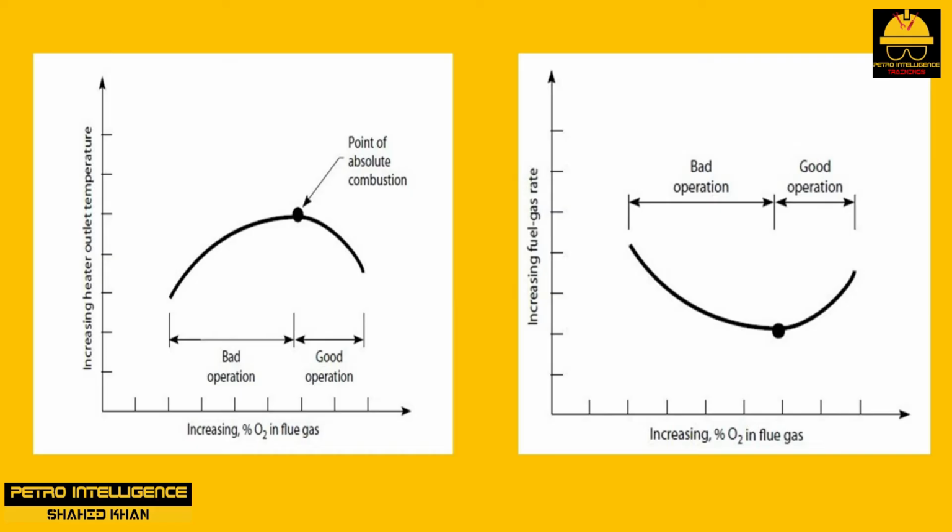Our normal heater outlet temperature target is 680 degrees Fahrenheit, but while I had all 3 blowers on, the outlet temperature rose rapidly to 740 degrees Fahrenheit. Rather than cutting the fuel gas back to reach a 680 degrees Fahrenheit outlet temperature while increasing excess oxygen, he shut down the 3rd blower and dropped the furnace temperature back to 680 degrees Fahrenheit, but also continued to run fuel-rich, without enough air. Which is cheaper, air or fuel? Of course, the answer is air.